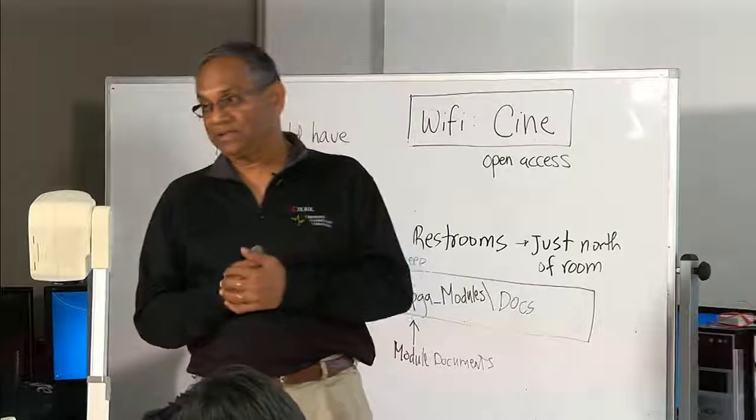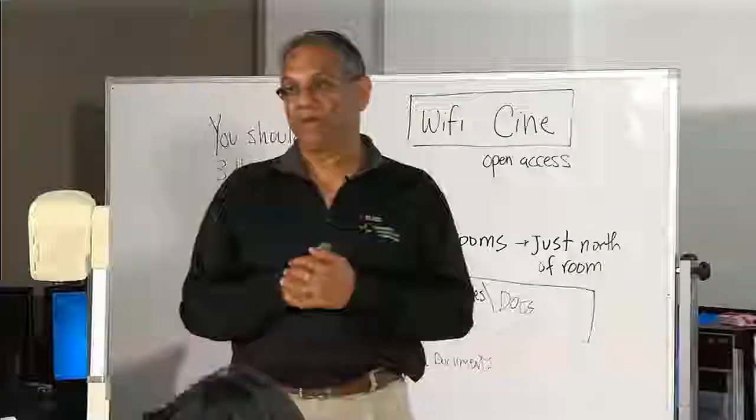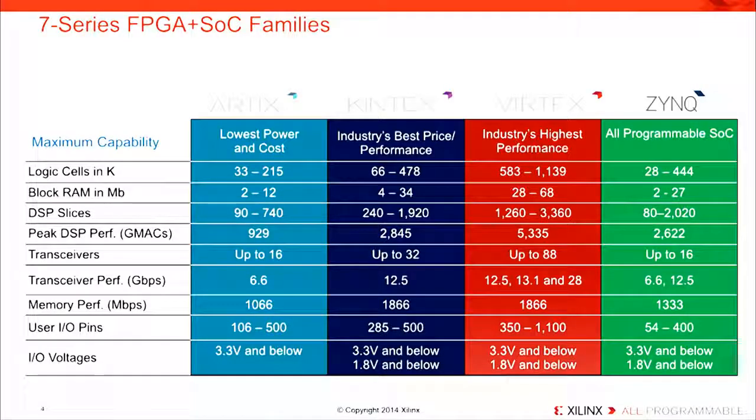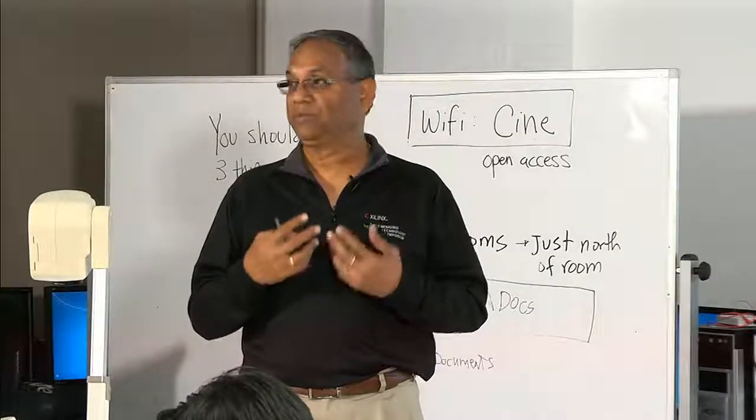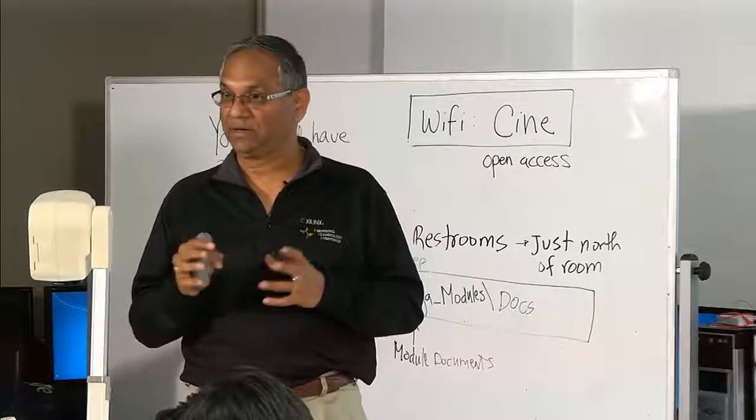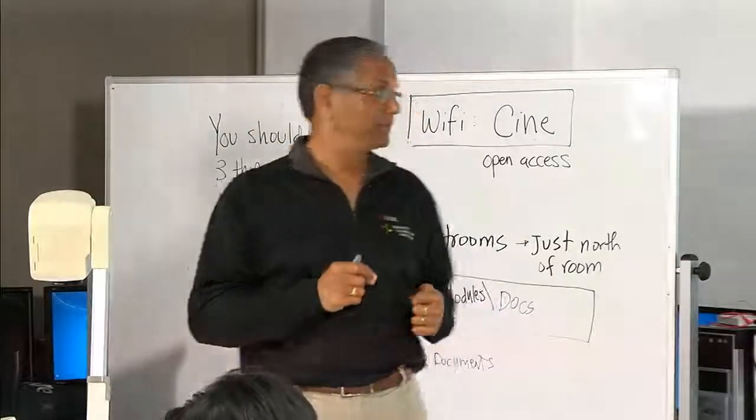So in the 7 series, we have a total of 4 subfamilies, out of which 3 are FPGAs and 1 is classified as SoC. Okay? FPGA means it does not have a hard processor IP block. You can put a soft processor like what you are doing here in MIPSfpga as a soft core, you can do that. And then Zynq is classified as an SoC because it has the processor hard IP block, not only one but it has 2 processors and it has many more peripheral controllers, okay, which we will see towards the end of the module.